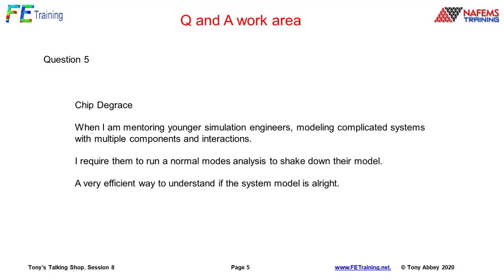If I'm dealing with, let's say, a complicated mesh, I'm using linear bonded interfaces to make sure it's all hanging together properly. There's really no better way than to run a normal modes analysis to see that the structure's hanging together properly. And again, it can give you some insight. As a designer, you can see where the stiff load paths are, the more flexible load paths are by doing a normal modes analysis. So I like the idea of extending this idea into other solution types.